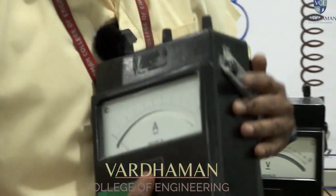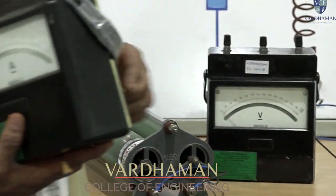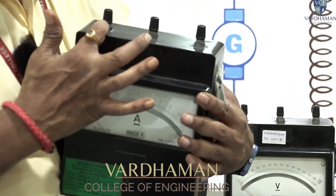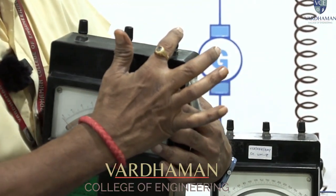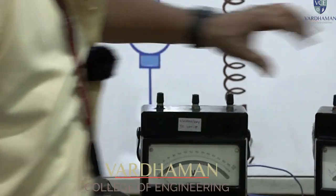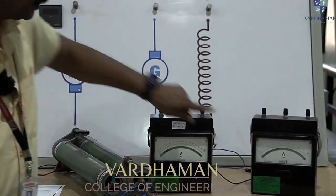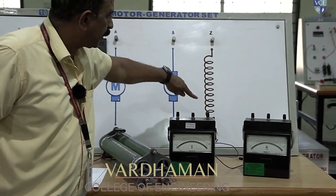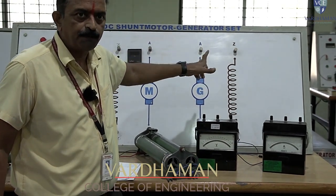Since our excitation current we have already seen is 0.48, I need to take the 1 ampere range. So this terminal I will connect in the magnetic field coil. As I am varying this rheostat, the current also varies. When the current increases in the magnetic field coil, it increases the amount of flux.